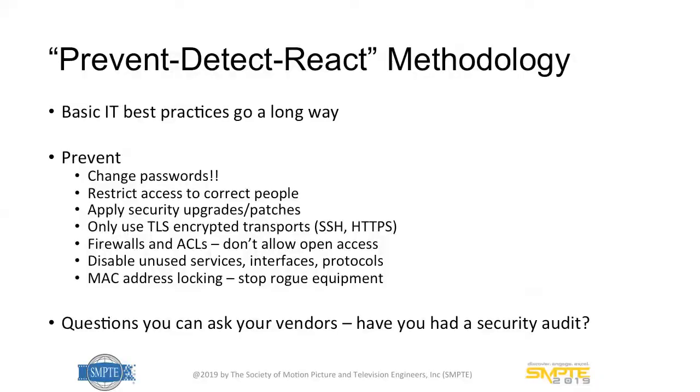That can be quite a challenging one for our industry because once you have a system that's working, a lot of people are very reluctant to upgrade it. I don't want to install the newest patch because it might break my system. But from a security point of view, it's very important that you're updating your operating systems and your software patches, because once they come out, attackers know about them, and then they know there are vulnerabilities. You want to make sure you're using secure communications, using firewalls. You want to make sure to turn off services. You should be using things like SSH, so you want to make sure to turn off Telnet, which is not secure.